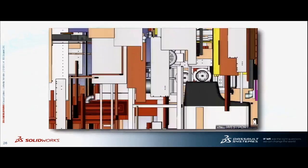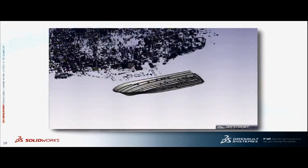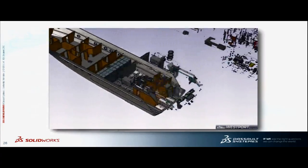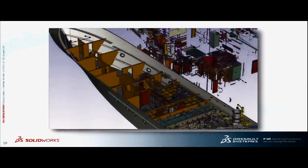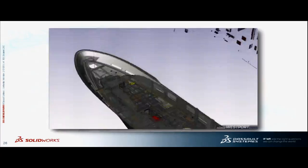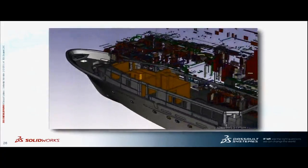That state is exactly where that component resided in the assembly at the time that it comes in from the CAD system. We can call it whatever, regardless of CAD system. What they did was they took the entire assembly, moved it off into space, and then they took what we call a spherical explode, which takes the center of the bounding box and explodes everything literally straight out. And then they took the hull itself, shifted it back to its neutral state so that it's sitting there. Every component, you see them coming in as units of things.